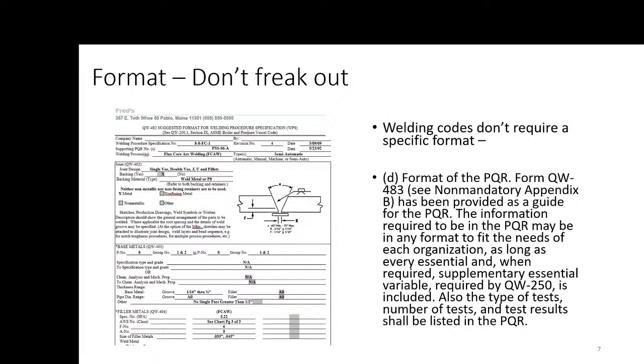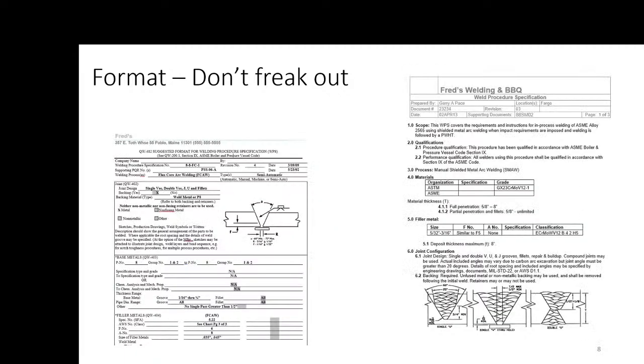So anyways, on the format, if somebody sends you a format you've never seen, don't flip out. As long as they address all the essential and, when necessary, supplementary essential variables, and they give you all the testing data, you're good. So, there's different formats here.